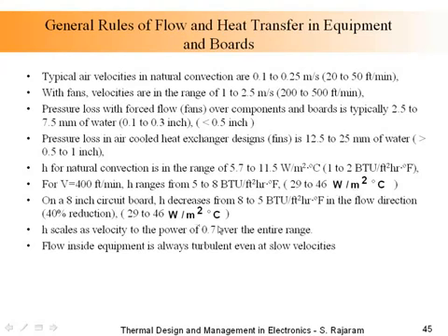So when you have a board that is 8 inches high, which is 200 millimeters, and there is air flowing around on that board, the heat transfer coefficient will decrease from the bottom of the board to the top of the board. Most of you who are heat transfer people who have studied fluid and heat transfer can recognize this, because the reason this happens is that boundary layer effect. As you know, at the leading edge, the heat transfer coefficient will be high, and over the trailing edge, it will be low. And so what happens is cooling reduces by about 40% as you go over a 200 millimeter airflow height. And this is important because when you have a reduction of H, you're going to have an increase in temperature.